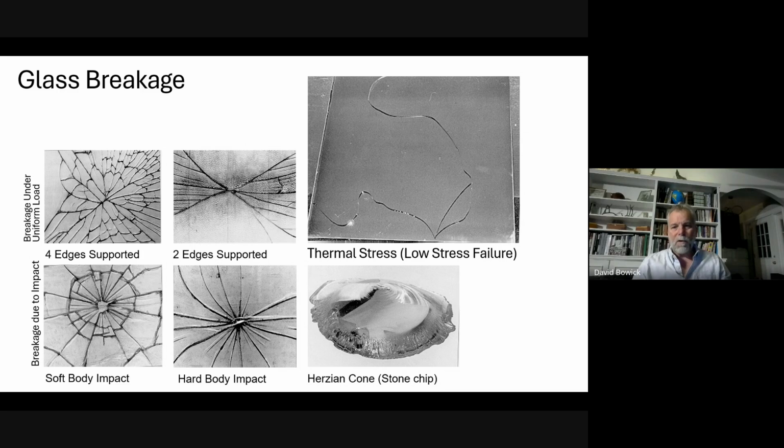So the important thing is that we recognize thermal stress or thermal failure. As soon as you recognize it, it's obvious what caused it. And I remember asking a window supplier, "What do you do about that? Do you just design everything with higher strength glass?" Because thermal stress is somewhat unpredictable. We can't evaluate how much thermal stress there is going to be in order to prevent it.